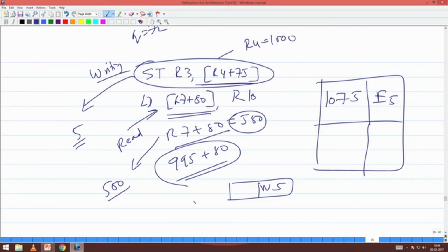So essentially what is going to happen, if I am going to have a content addressable memory like this, then I can handle the memory aliasing problem also, like the way I handle the register issue. All the WAR, WAW and RAW can be handled like this, correct, and the operand forwarding also happens, your renaming can also happen.